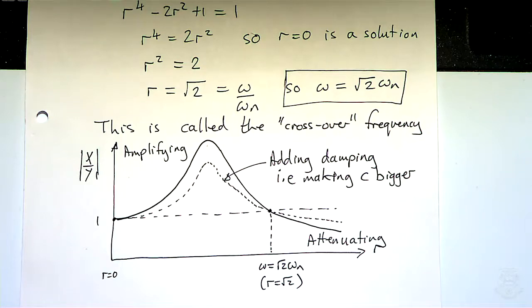These kinds of vibrations are interesting, particularly for aerospace engineering, from when you've got cabin vibrations happening from engines, either in helicopters or fixed wing aircraft or whatever. This is all coming as a kind of support input, if you like. The fuselage or the cabin is being excited by something which is basically attached to it and is shaking it. It's acting like a source of vibration. So this kind of transmissibility design is quite important.